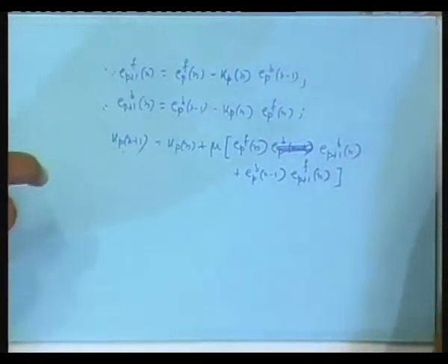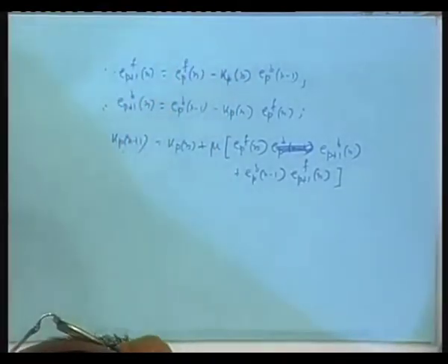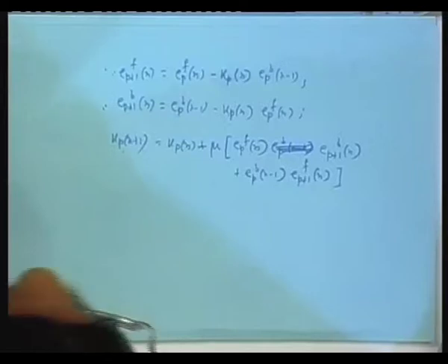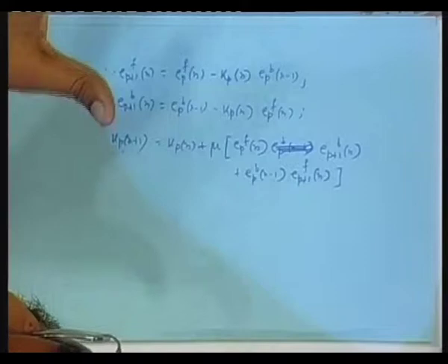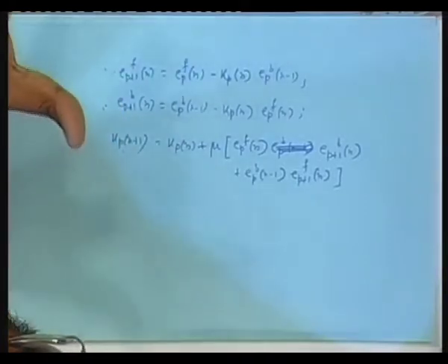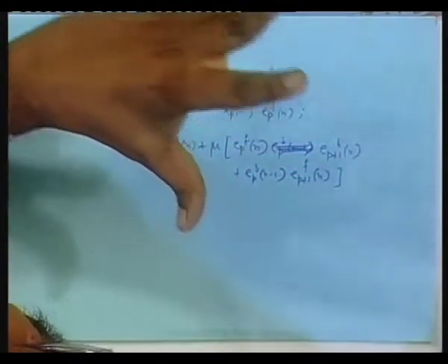So, that is all for this kind of business. This is called stochastic gradient treatment. We basically take the gradient of that error, and this is a stochastic gradient because it is dependent on the data finally in the LMS case. It is not just dependent on constant quantities like the R matrix and P vector, but when you move to LMS it involves data, and therefore it becomes a stochastic gradient because it is just taking the stochastic process and evaluating a gradient.